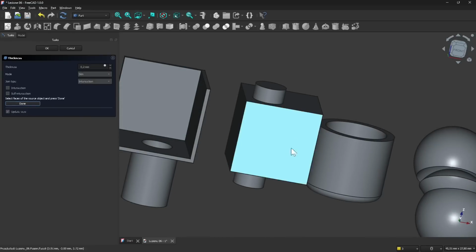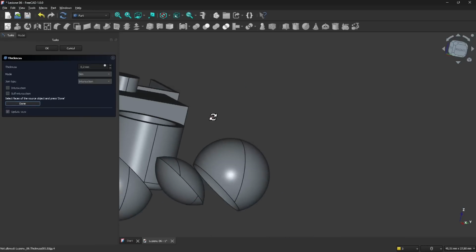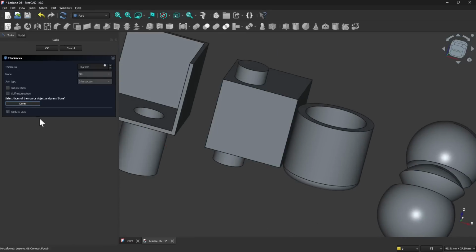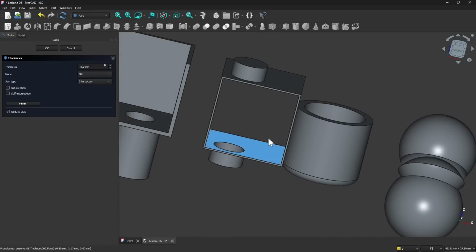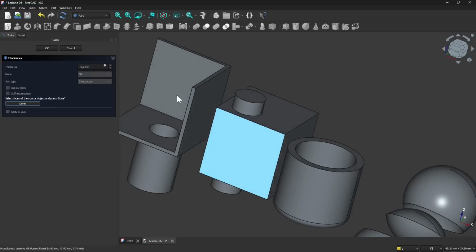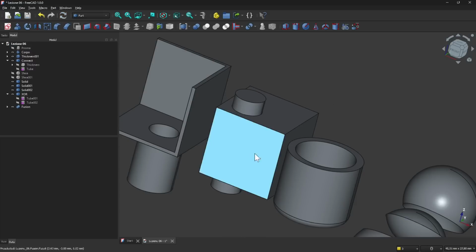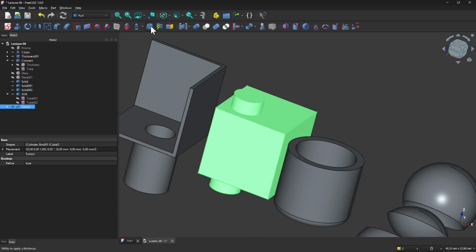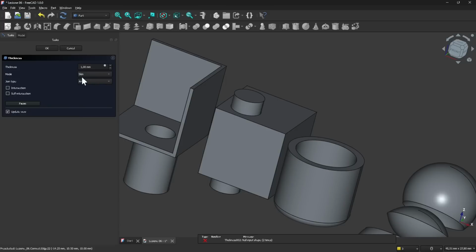Okay, if we go here and do not choose any face, and we say done, well, let's go here, for example, and let's delete this and go back to the original fusion and do the thickness. So skin again, and intersection, thickness, let's do like minus 0.2. Okay.